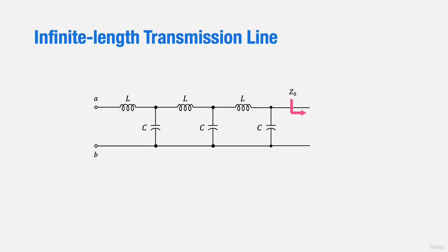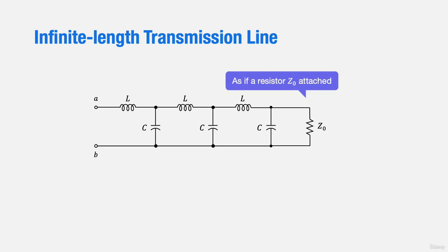The distributed circuit model of a line shows that wave propagation depends on the charging of a series of inductors and capacitors by a signal source. The real value characteristic impedance signifies propagation along the line. This is because it is as if there is a resistance on the right side of the line that is continuously receiving the transmitted energy.